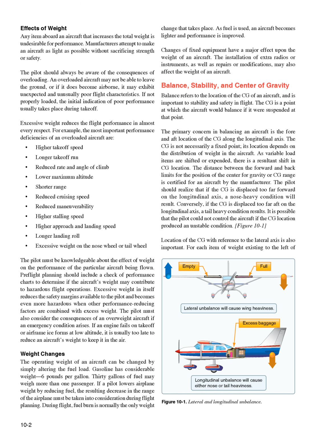The pilot must be knowledgeable about the effect of weight on the performance of the particular aircraft being flown. Pre-flight planning should include a check of performance charts to determine if the aircraft's weight may contribute to hazardous flight operations. Excessive weight in itself reduces the safety margins available to the pilot and becomes even more hazardous when other performance-reducing factors are combined with excess weight.